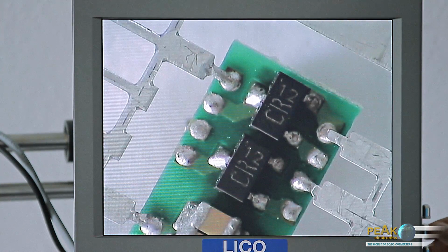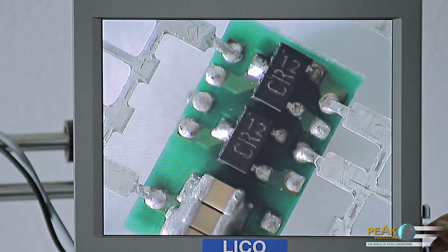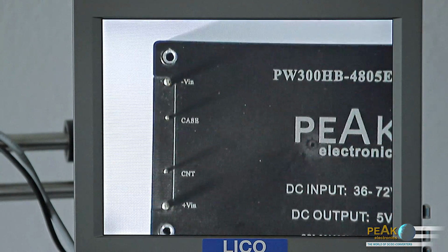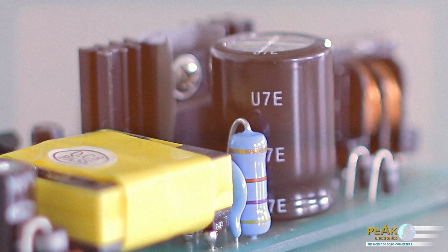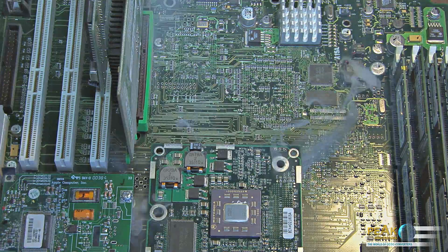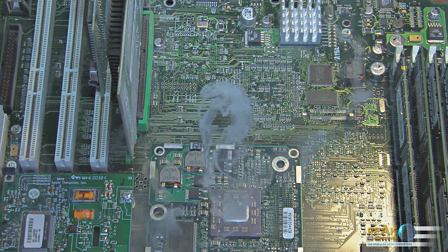And the input protection. Building in input protection is always recommended. With the destruction of a converter through an external influence, a short circuit can be created in the input circuitry, which causes a correspondingly high flow of current. The result is that the converter literally burns out, or smouldering of the leads is caused.